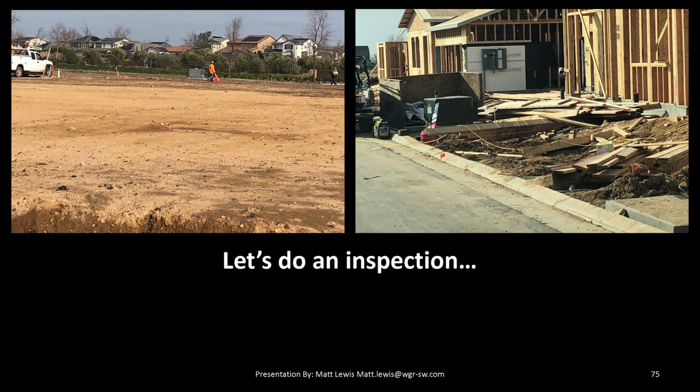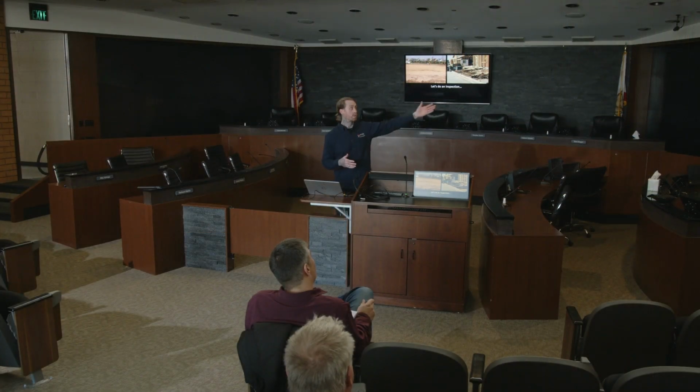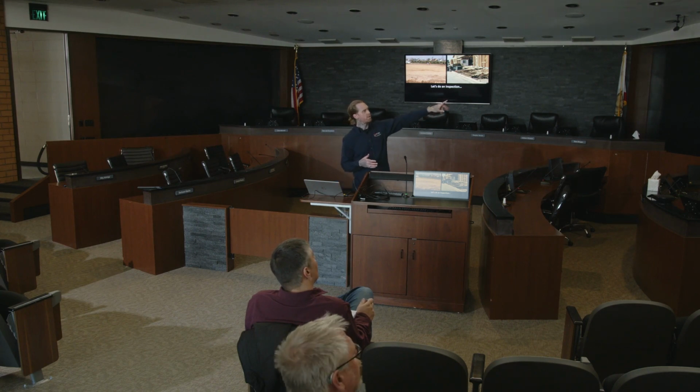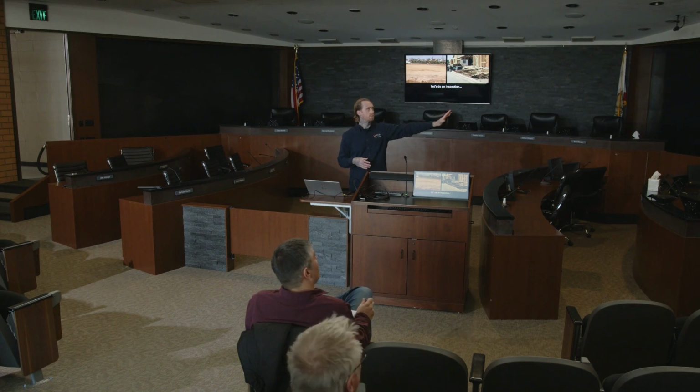And now I realize with the left one that I probably should give you another cheat. I'm pretty sure I mentioned it, but when it comes to exposed soil, generally after 14 days of inactivity we want to require some sort of erosion control, because this was during the summer, a really windy area, just tons of wind erosion. So this is a thing that you will always fight with your contractors over, and they will probably never do it. This site, for instance, is hundreds of acres,